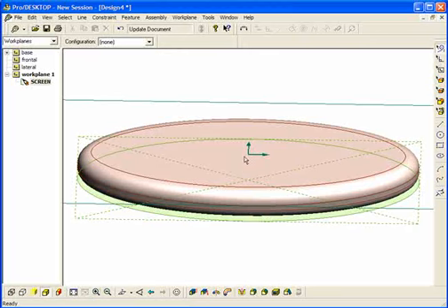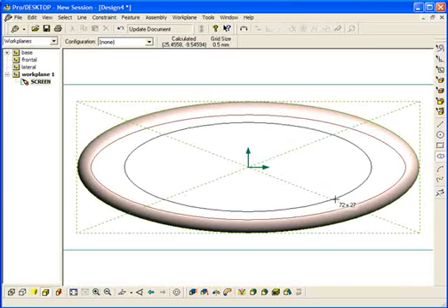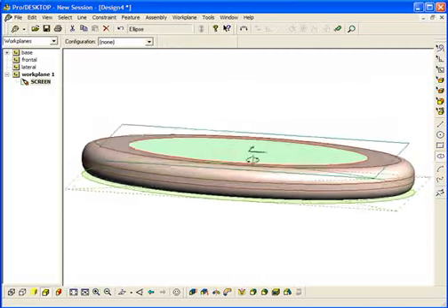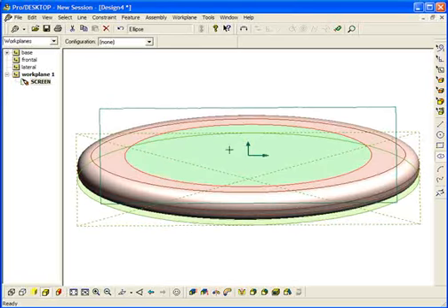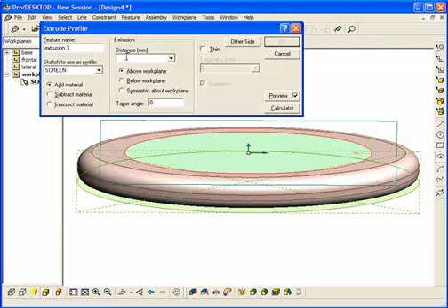We can always now draw another shape or sketch for your screen onto this shape. Click on the View on the Work Plane tool and again use the ellipse tool and draw out a new shape for your screen, this time an ellipse. Double check it is on the correct surface and that it is filled. Then again, Feature Extrude. I shall extrude it above the surface this time. Again, 0.5.